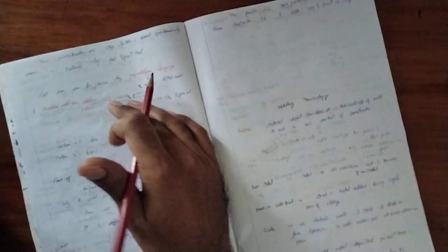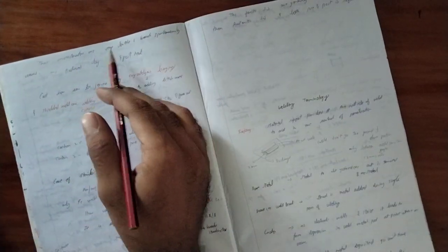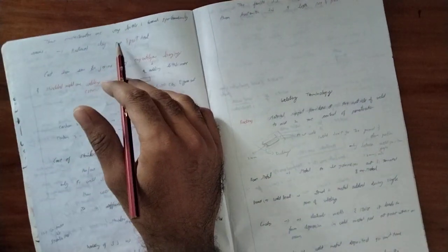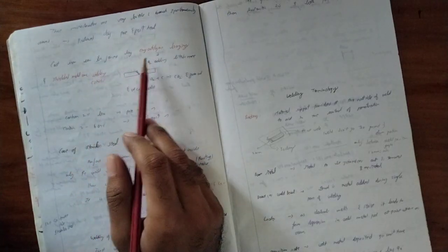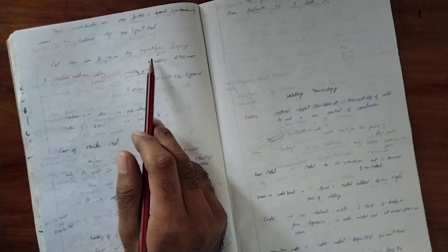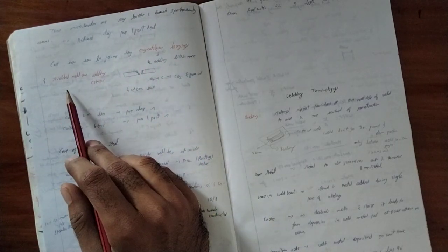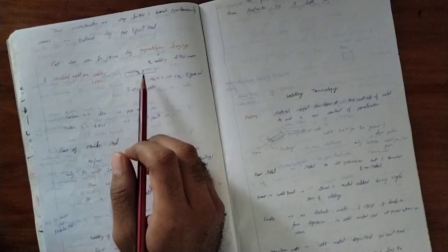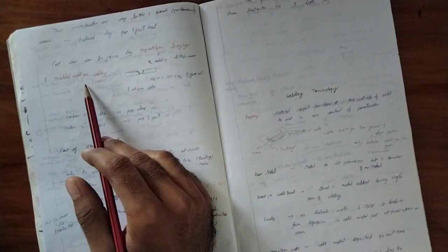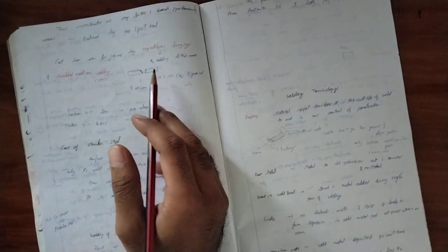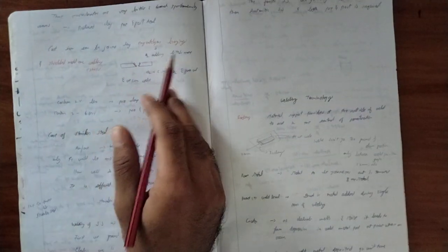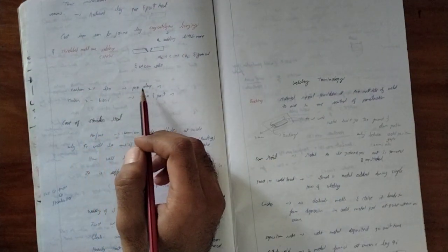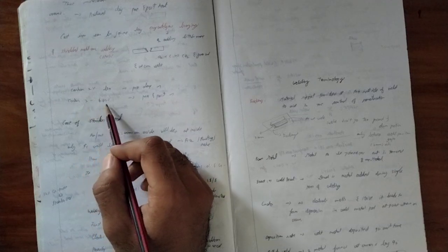So next thing, you can see this microstructure is very brittle and cracks spontaneously, and is reduced only by pre and post heating. Cast iron can be joined by oxyacetylene brazing and shielded metal arc welding. Okay, oxyacetylene brazing and shielded metal arc welding, and you can see oxygen adding a little more, and this one here. So carbon less than 2% needs less preheating, and carbon 2 to 6.6% needs preheating as well as post heating.